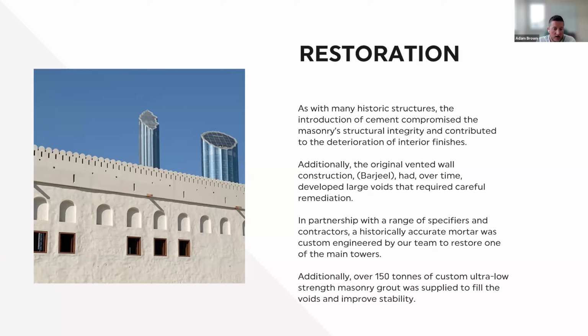Due to more modern interventions and additions, they started to find severe structural issues within the walls of the fort, and they were quite worried about collapse. As part of our remit, we were contacted by both engineers and specifiers involved in the project, and in partnership with our lab team, they wanted us to develop a custom lime-based grout that could be pumped into the walls to provide stability.